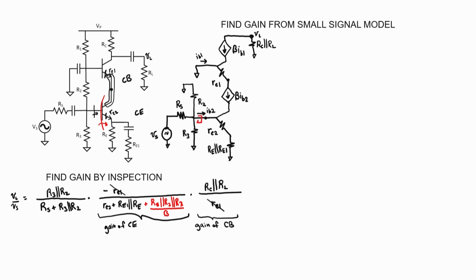Let's now simplify our source a little bit by replacing it with a Thevenin equivalent source and a Thevenin equivalent resistance. The source will be providing the same base current as it was in the last drawing, IB2. I'm now going to combine these two resistors into one, and I'm going to just call it R sub lowercase e.